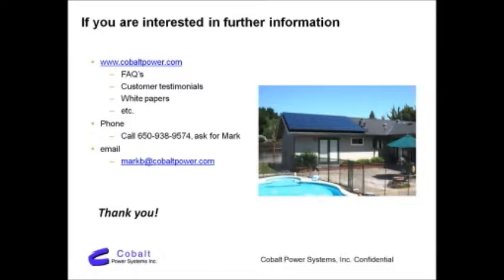Even 5 and 12, 3 and 12, 6 and 12, it just doesn't matter too much. Even completely flat is 0.89. So you only lose 11% from the optimum and maybe like 6 or 7% from the typical if you put them completely flat on a flat roof. So it just is not very critical. But we take all this into account when we quote a system. Okay, great.